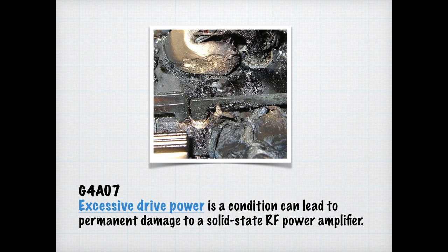Here we have a photo of a burned up power amplifier. Take a good look at that because you don't want that to happen. It's an expensive repair. For the exam, you need to know that excessive drive power is a condition that can lead to permanent damage to a solid state RF power amplifier. So don't turn it up all the way.